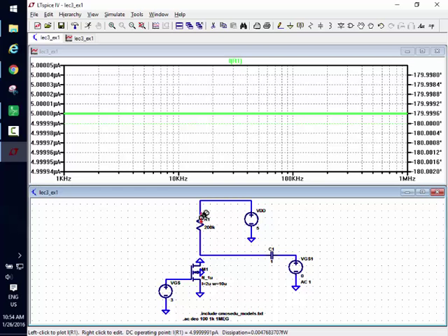How do I know it's -5? Here's the phase shift. Remember, it's AC. It's 180. Here's the magnitude. It's 5. Does that make sense? Of course, if I define the current flowing the other way, then it's +5, just like I said with 0 degrees phase shift. Yes.